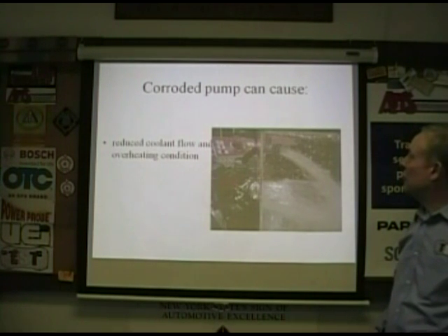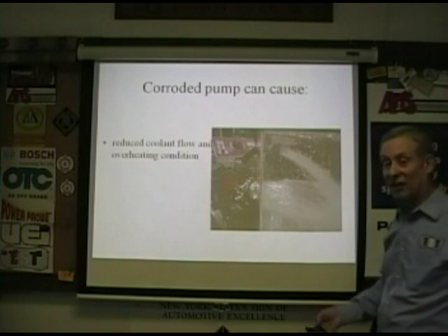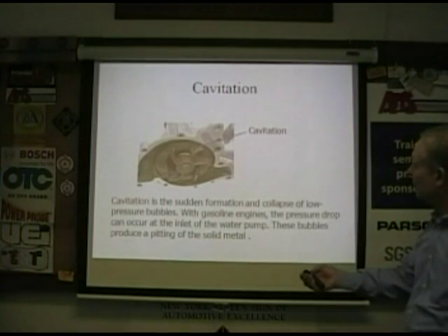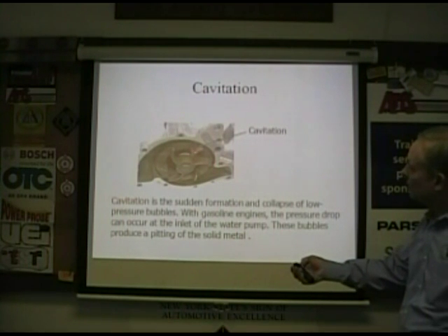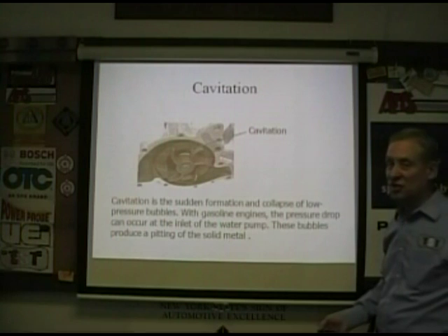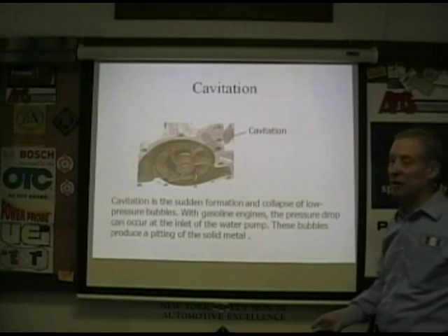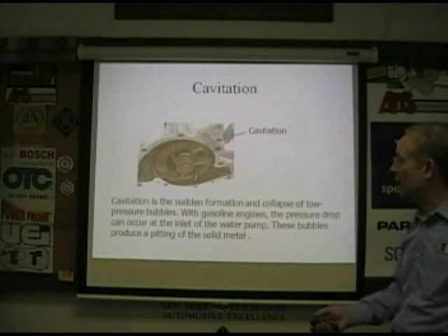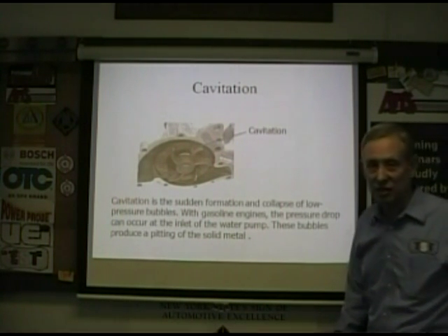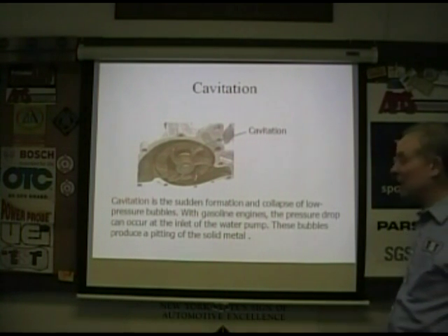All right, reduced coolant flow and overheating. We can get corrosion. This is stuff we kind of know, basic stuff. You don't want problems with it. There's an impeller with pitting, that's cavitation. The bottom line is there are pits in the impeller, and that happens because it's not just coolant makeup, it's pressure also, it's flow restrictions. You end up with such a big pressure change that there are air bubbles in there, and they literally explode on the surface. Exploding air bubbles cause damage. And by the way, sounds crazy.